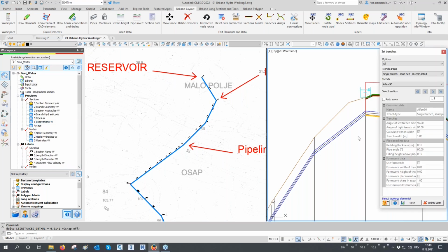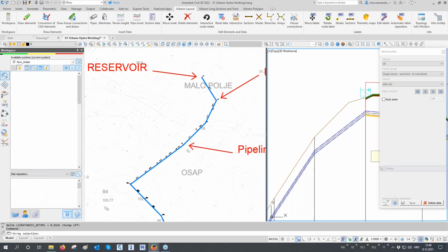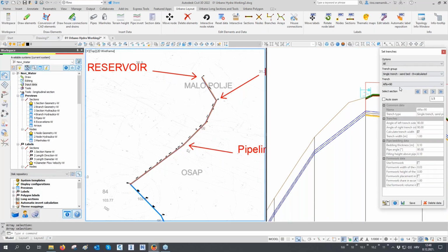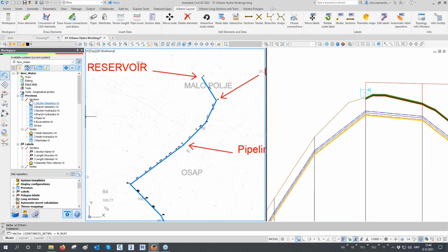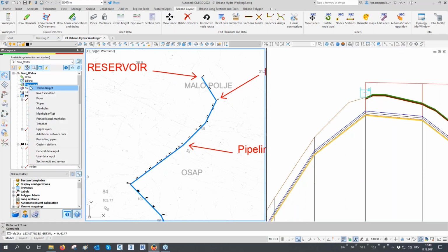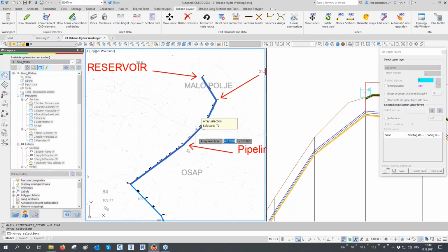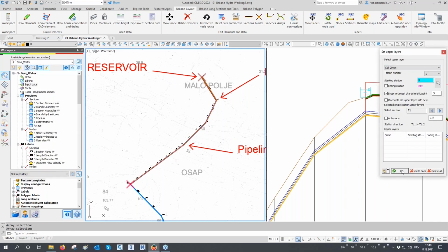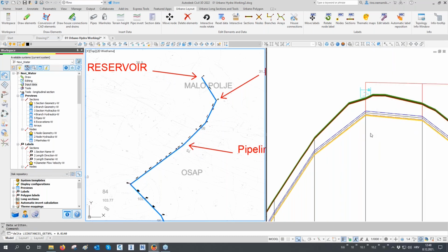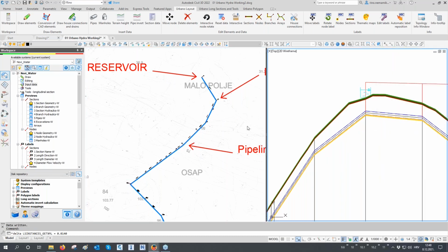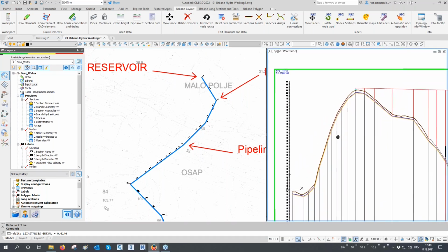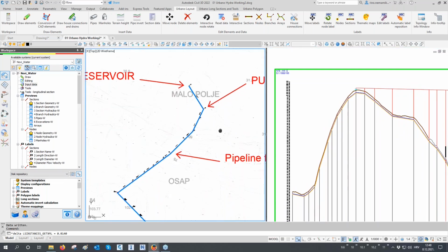Let's go to trenches. Let's select this array. Let's set the same trench as yesterday. Let's click save. Okay, let's go to setting of the upper layer. So input data, upper layer. I will use again the soil of 20 centimeters. Let's select this array and let's click save. Okay, and now we have everything defined. Okay, so now as we see here, we have to also define reservoir, pump, and that's it.